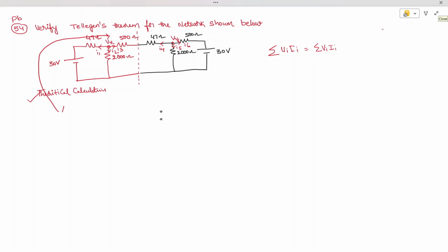So here we are going to apply nodal analysis at node Vx, which is indirectly applying Kirchhoff's current law at node Vx. Here you can see, are there any entering currents? No, all are leaving currents. So I can write entering currents is equal to 0. The leaving currents are I1 plus I2 plus I3 is equal to 0.